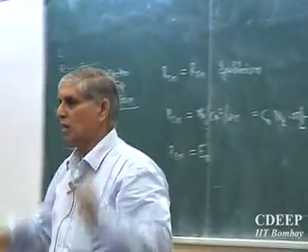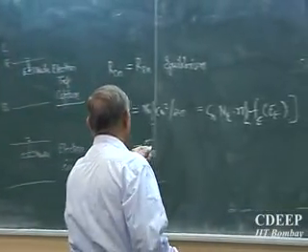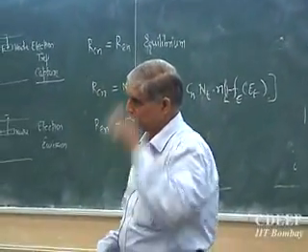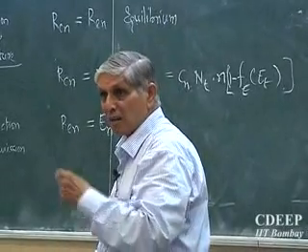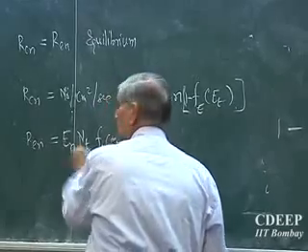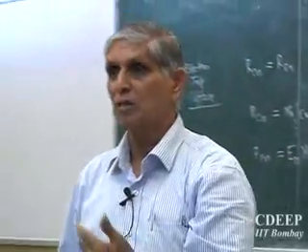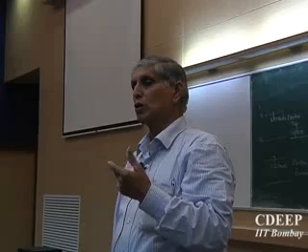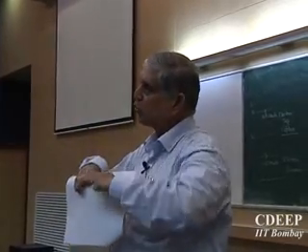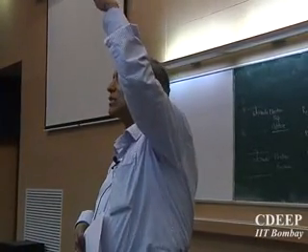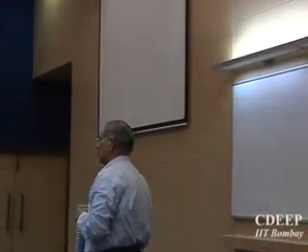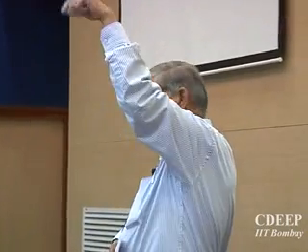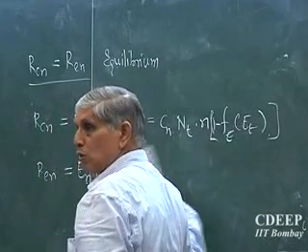On what will it depend? Let's say traps are filled now. How many traps will be filled? Let's say NT are the traps, and all of them are filled. Now emission is to occur. So what probability should I use? That they are already filled. So NT into FT at ET is the probability that these electrons can emit from the trap levels, whose maximum number is NT. So it is not proportional to N. Why? Because these many carriers are already filled there, and they only can emit. At best you can say it depends on available states, but available states in the conduction band are much larger, so we don't look for that number now. All of them can go there and there will still be enough states. So this is not proportional to N, whereas in capture, I must know how many can come. However, in the case of equilibrium, this number is equal to this number.